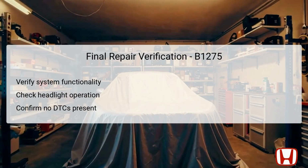Final repair verification involves ensuring that all systems are functioning correctly post-repairs. This involves retesting the headlight operation to confirm that each of the DTCs B1275 through B1278 has been addressed effectively. Utilize the HDS to check for any remaining DTCs and confirm that none are active. By ensuring that the headlight operates according to vehicle specifications in all switch positions, you can affirm that the previous repairs were successful. This step should include road testing the vehicle to confirm proper functionality before concluding the repair process.